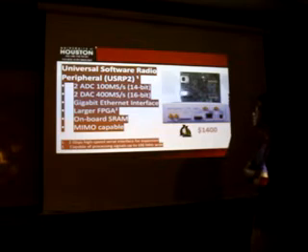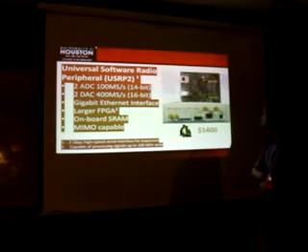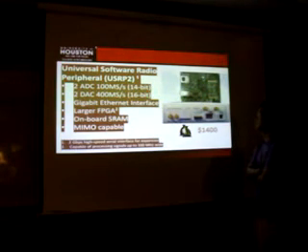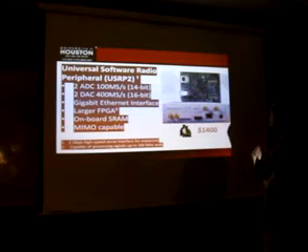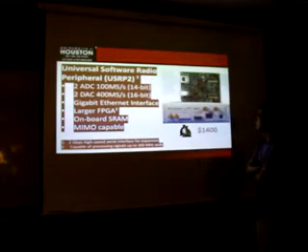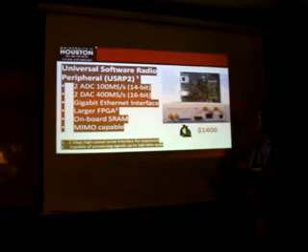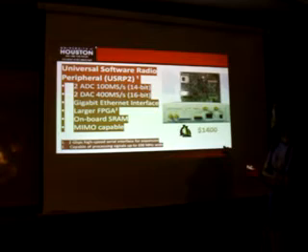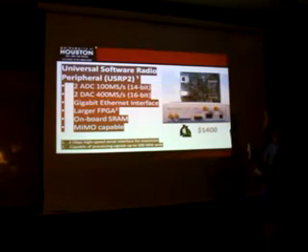Here is the hardware architecture of the USRP2. USRP2 has 2 ADC and 2 DAC. The speed is much faster. USRP2 uses a gigabit Ethernet interface to connect with the computer, because the bottleneck for the USRP1 is the USB interface. The speed of the USB interface is too slow, so for USRP2 they replaced it with a gigabit Ethernet interface.